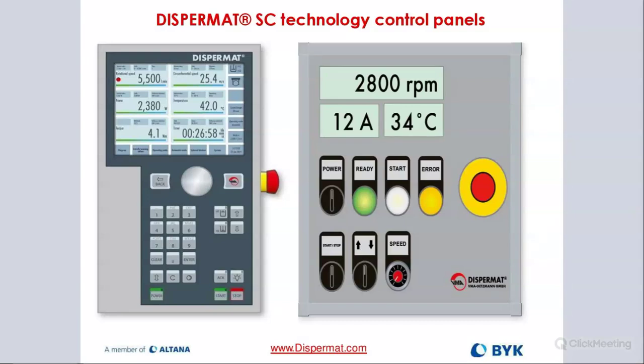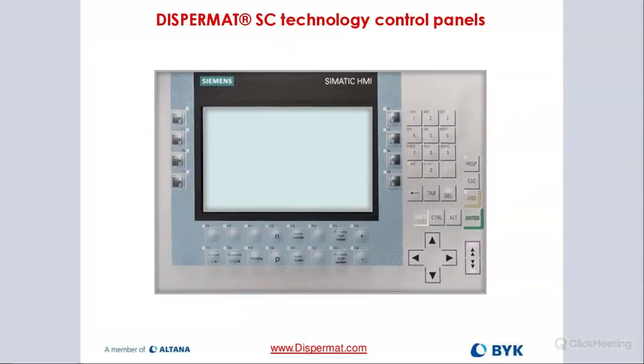You can also program recipes with the C technology, allowing you to lock in all these values and then basically give the batch a name or an ID number. And then the next time when you're running this product, you're able to replicate it exactly the same way for consistency and repeatability. So that way you can be sure that the product will always be produced the same way, and that the particle size and everything should be constant if the process remains the same. So that's a big advantage of the C technology.